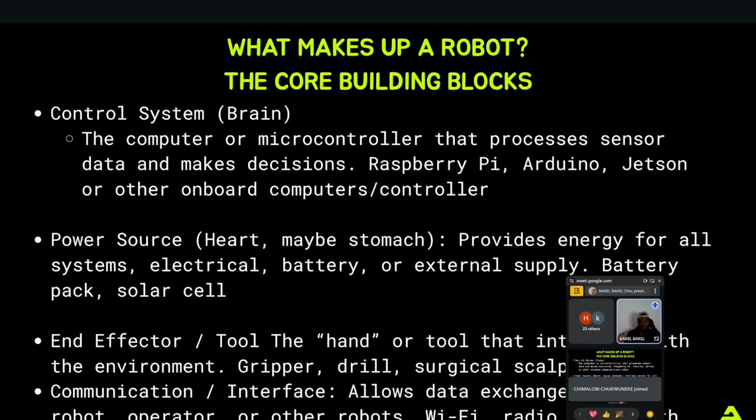If we move on to the next slide, we see control systems. The most common ones are Arduino and Raspberry Pi. There is a robot arm that uses one Arduino. But you see Unitree Go 1. Unitree Go 1 is that robot dog by Unitree. It uses 4 CPUs. It has an ARM CPU, and then it has 4 other NVIDIA CPUs. Why? Now you can see that there's a lot of computation that is needed for that kind of robot. Whereas your Arduino robotic arm, you really don't need much. At most, you are moving 4 motors or 5 motors. So you do not need much.